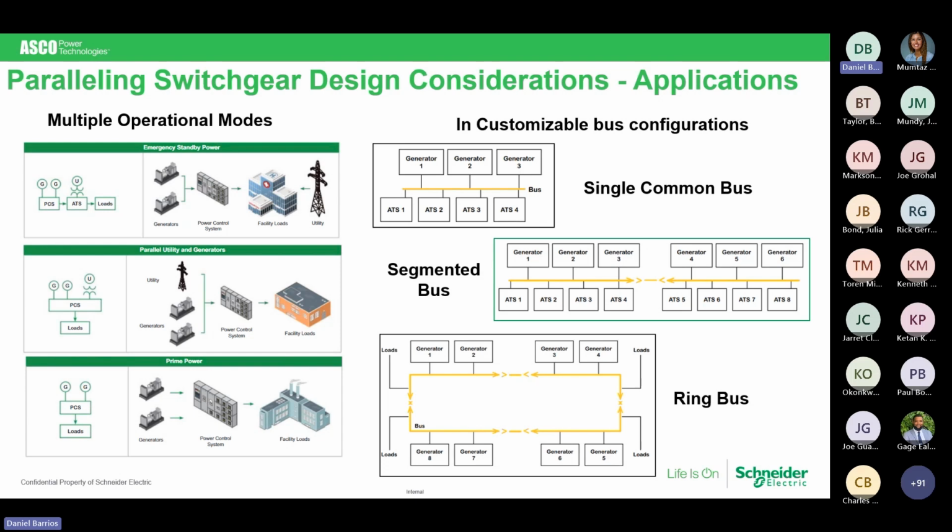Segmented bus, very much so in medium voltage, but depending on where we're looking at here, when you're looking at generators 1, 2, 3, 4, 5, and 6, if you have priority 1 loads on each of those buses, or you have your priority 1 load separated because it's exceeding 1 generator, then what's going to happen is the first generator that hits is going to close your priority 1 loads on bus A on the left side.